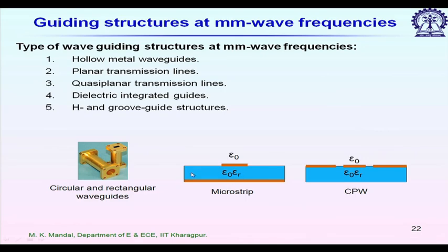This is actually showing the cross section of this transmission line system. This orange color is showing the metallic part, and this blue color is one type of insulator, we call it dielectric. It is showing its dielectric constant is epsilon r, and we will see later that at millimeter wave frequencies we can't use metal for power transmission. At 50 hertz we use twisted wire for power transmission. At megahertz frequencies we use parallel two wire system.